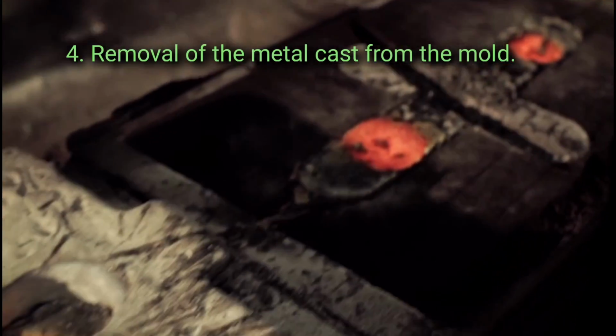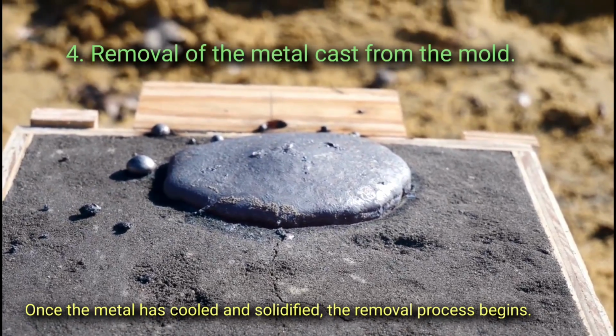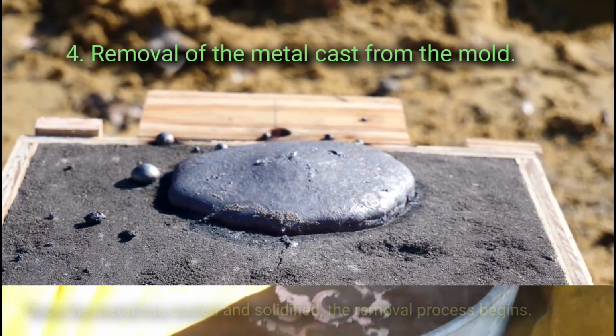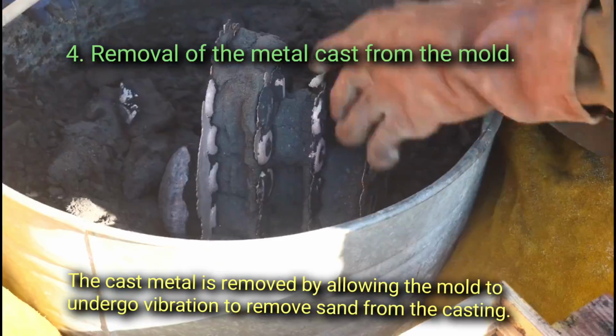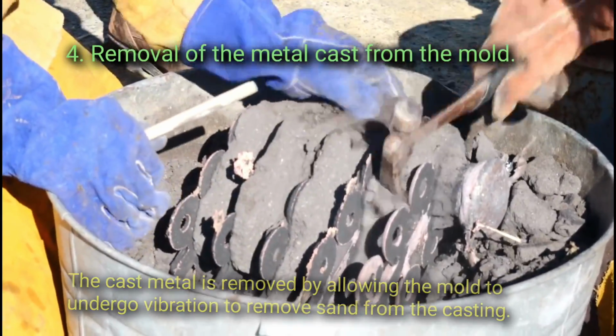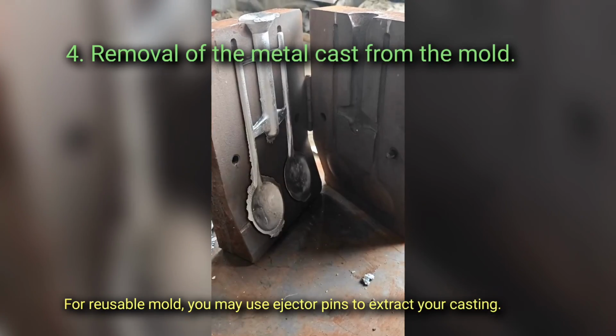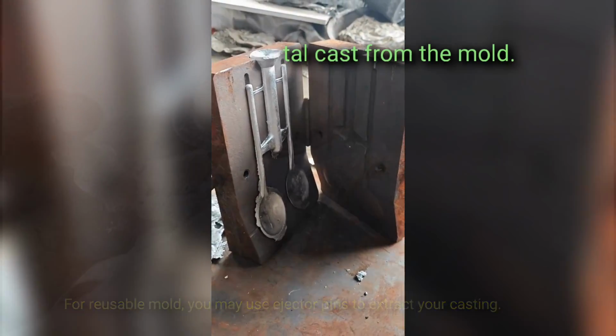4. Removal of the metal cast from the mold. Once the metal has cooled and solidified, the removal process begins. The cast metal is removed by allowing the mold to undergo vibration to remove sand from the casting. For reusable molds, you may use ejector pins to extract your casting.